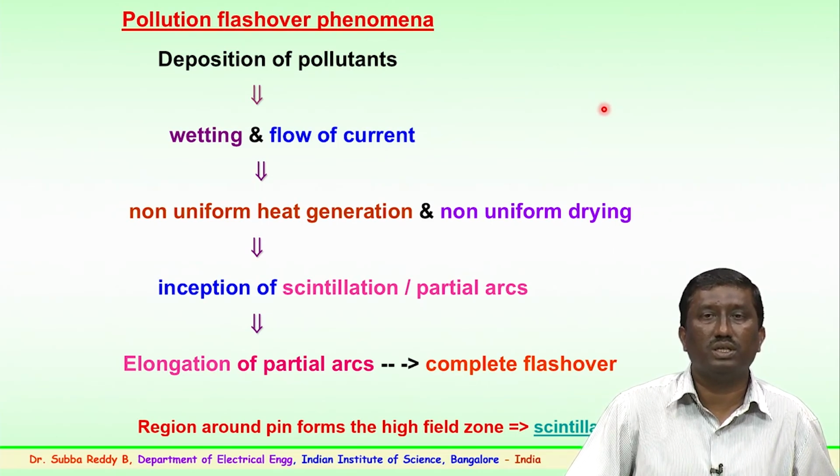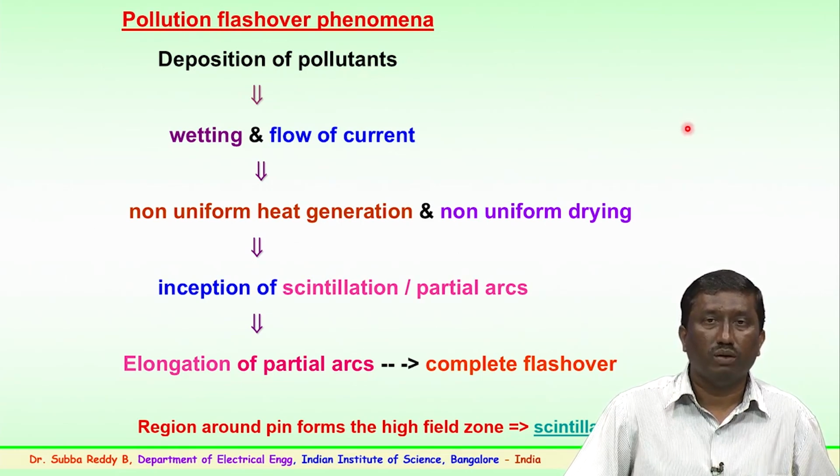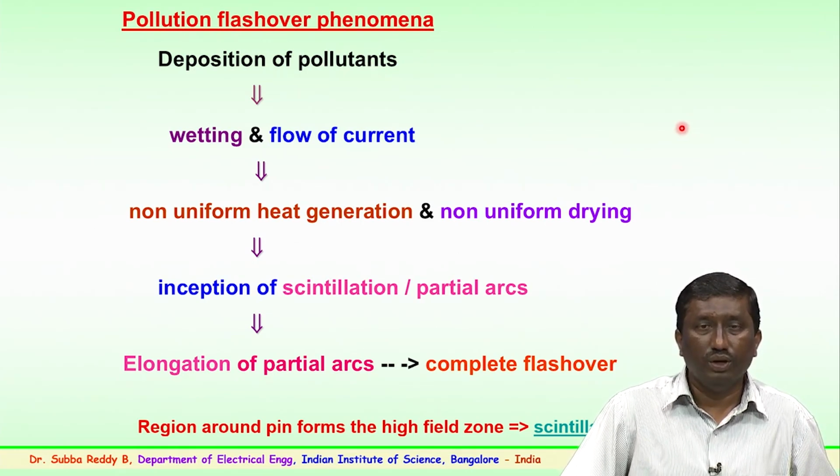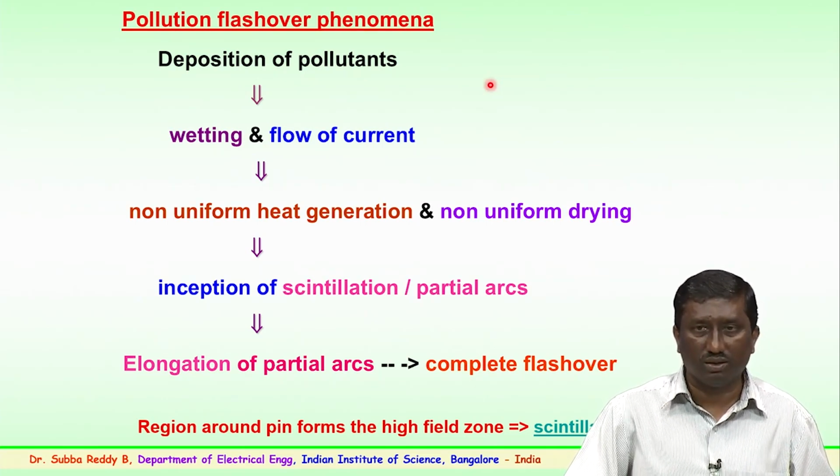In case of industry, these are industrial pollutants; for towers or lines passing near the sea coast, sea salts could be the pollutants; or in agriculture fields, agriculture-related pollutants could settle on the surface of the insulator over a period of time. Because of pre-monsoon conditions or high humidity, this becomes wet. So, mist because of fog, or light rain, makes the surface wet, and heavy rain is a complicating factor.